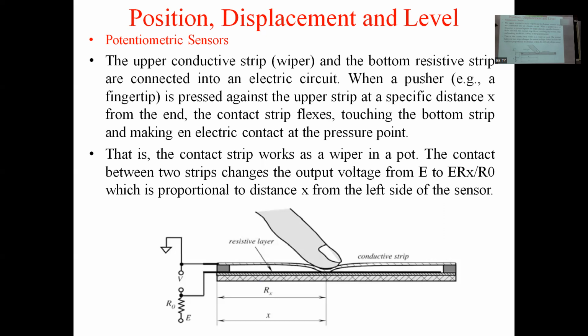जसं वायपर ची मगाशी आपण दाखवली त्याच्यासारखीच arrangement आहे. Here this conductive strip will act as a wiper. इथं जो वायपर चेंज होतोय because it is mechanically coupled to the object, तो वायपर मूव होतोय, म्हणजे रेजिस्टन्स चेंज होतोय, म्हणजे length changes, its resistance changes, its voltage drop or output voltage changes. So this is a potentiometric type of sensor. Okay.